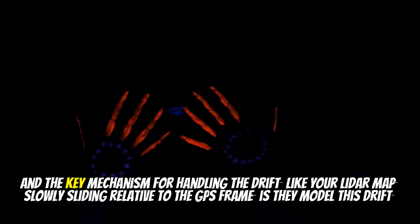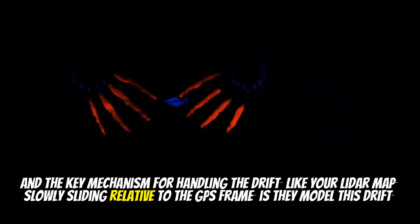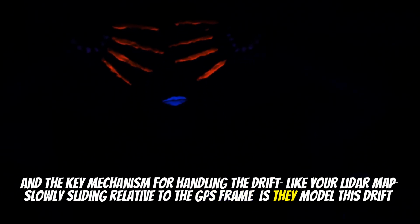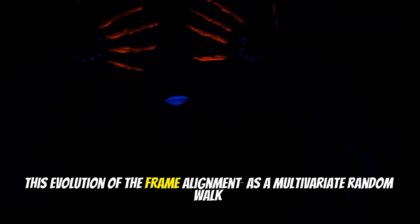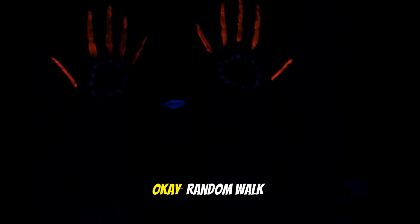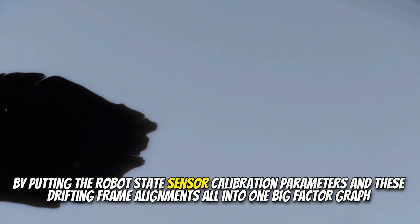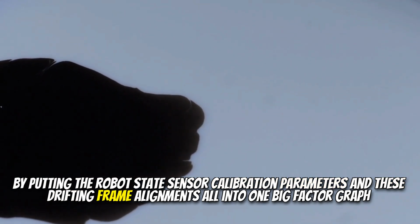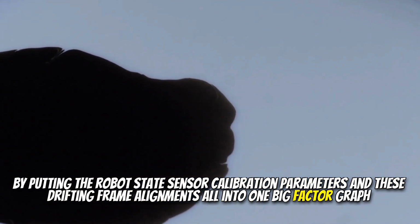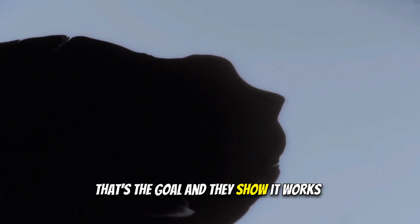Precisely. And the key mechanism for handling the drift, like your LiDAR map slowly sliding relative to the GPS frame, is they model this drift, this evolution of the frame alignment, as a multivariate random walk. Okay, a random walk. So it allows the frames to shift over time in a probabilistic way. Yep. By putting the robot state, sensor calibration parameters, and these drifting frame alignments all into one big factor graph optimization, they managed to get the best of both worlds. That's the goal, and they show it works.